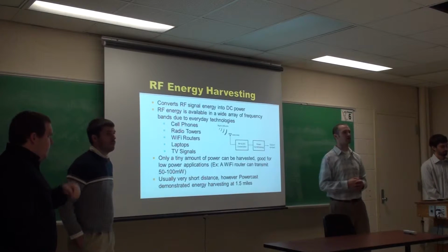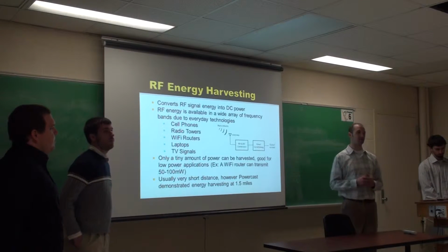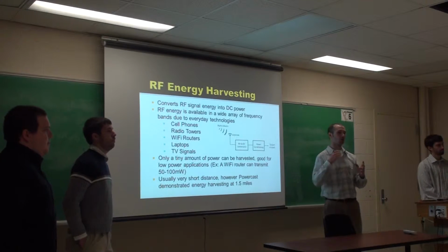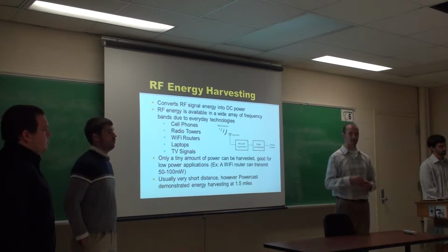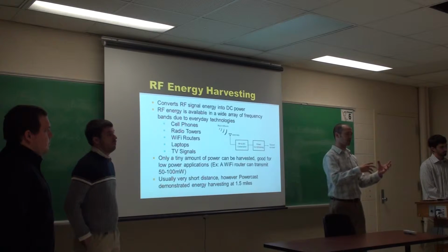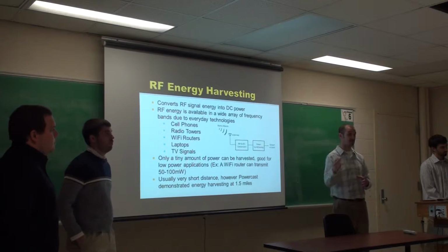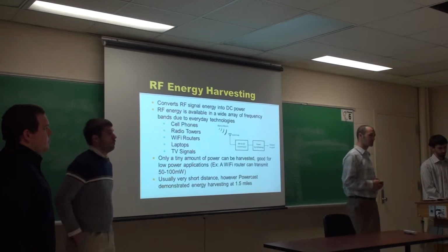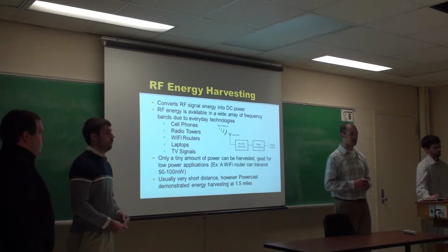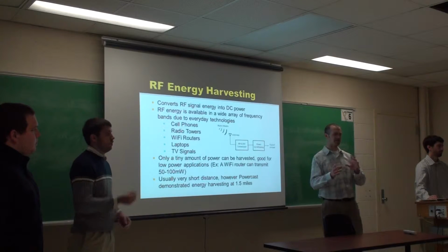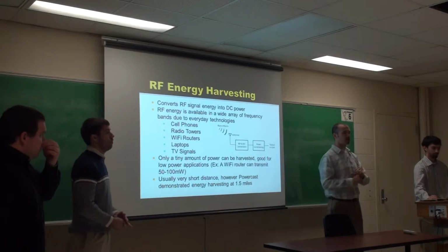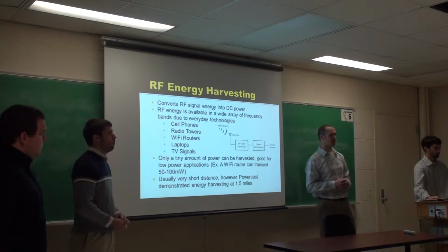Similarly to a lot of other energy harvesting techniques, this gives off a very, very small amount of power. So we have to use it in things like low power sensors or low power microcontrollers like our MSP430 that we use in lab, or other low power appliances that we can convert and also use very quickly since it is discharging a capacitor. So it's a very sudden power source. Similarly, this is a very short distance application. So we're talking on a matter of typically 5 to 10, maybe even as much as 30 feet. So usually, room to room size is how RF energy is getting harvested.